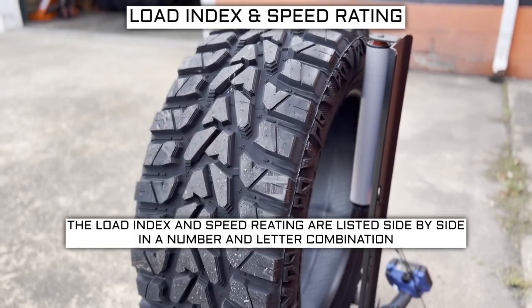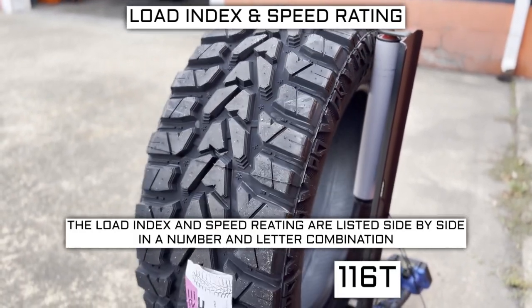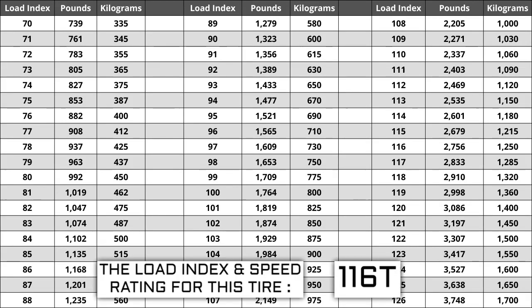Next to your tire size, you will see a number and letter combination like 116T. The number 116 is the load index. This is the number relative to the weight capacity of the tire. The higher the number, the greater the load carrying capability of the tire. Load index ranges from 0 to 150.